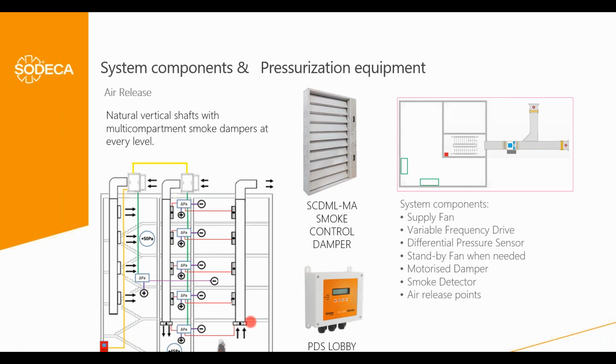Okay, and specifically in the fire level, this is one of the reasons also that the system has to be activated through, I will talk later, a fire detection addressable system, because we need to know on which level the fire is present to open only the window or the damper on that level. So for that reason, the system cannot be operated by manual call points that someone could press during evacuation, because we cannot know for sure if they will press the manual call point in the fire level.